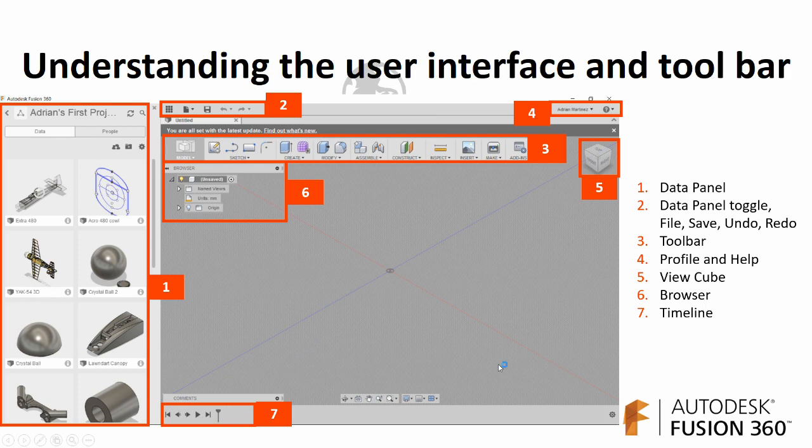So just definitely create new sketches wherever you're at in the timeline instead of going back to old sketches, because everything that happens after a sketch, for example, depends on the dependencies and everything else that's in there. So if you go changing things, it makes it really difficult for Fusion to infer what you really want to have happen on the things that have happened after that. So anyway, it all makes sense in a minute once we get into Fusion and start talking about that.